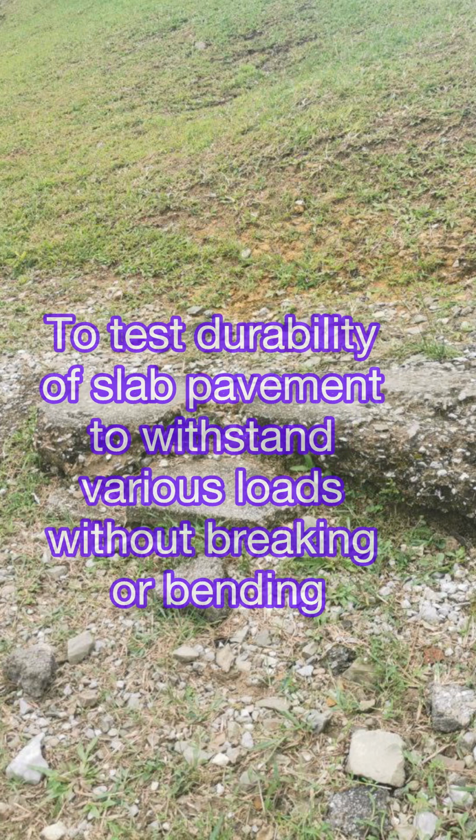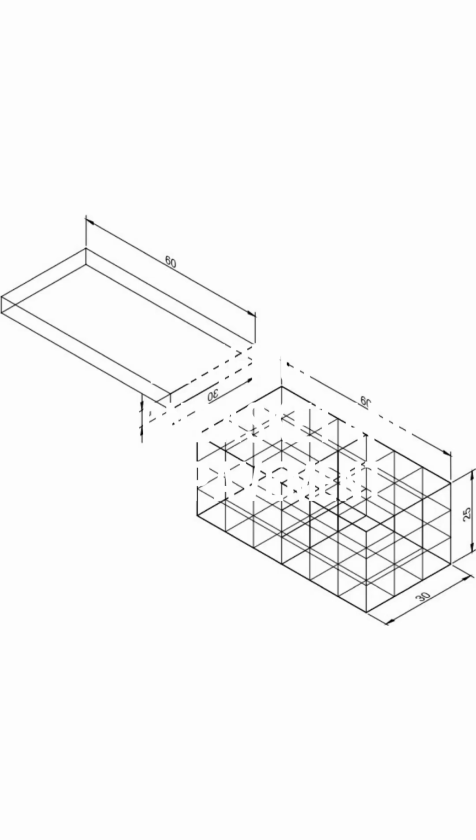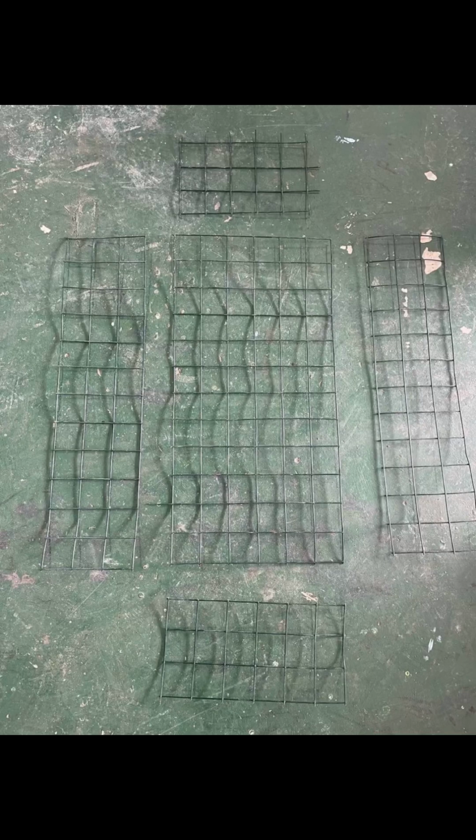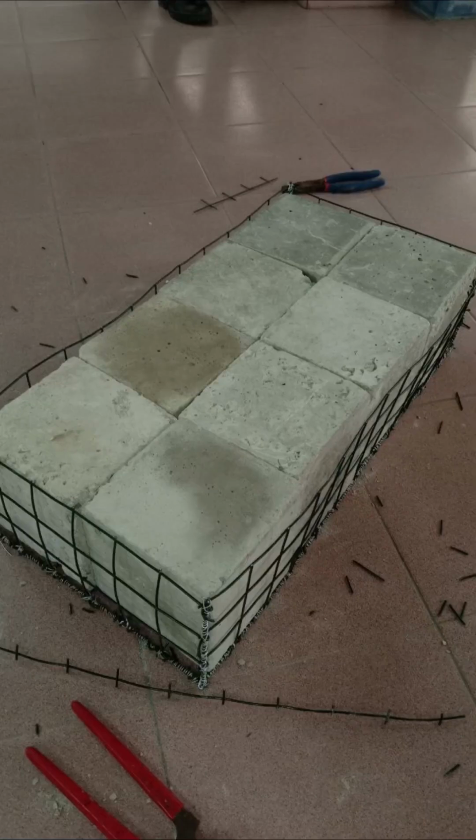Now, let's look at our design for Gabion basket and slab pavement. The size of Gabion basket is 300 x 250 in height and 600 mm in length. The Gabion basket is designed so that it can fit 8 concrete cube size 150 x 150 each. The first step was cutting the wire mesh into 6 sections according to the design. Each wire mesh piece is assembled to form a rectangular basket shape.